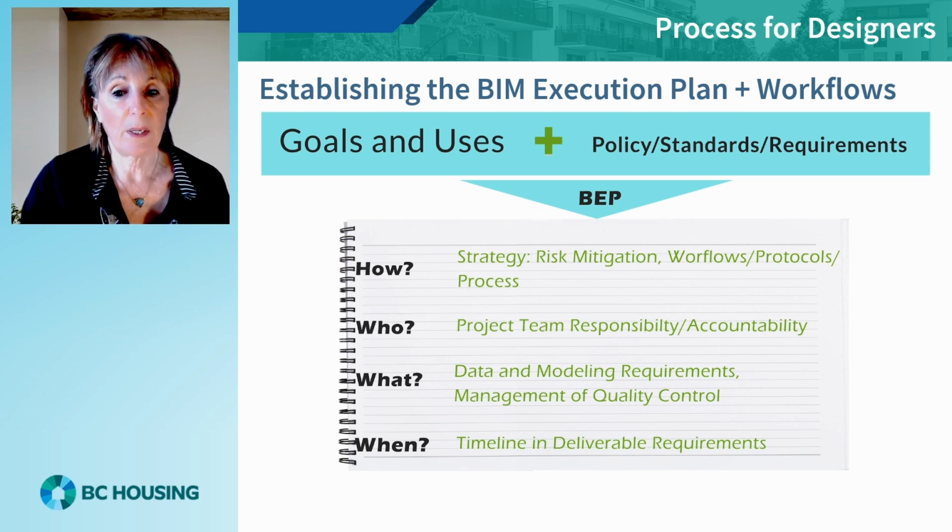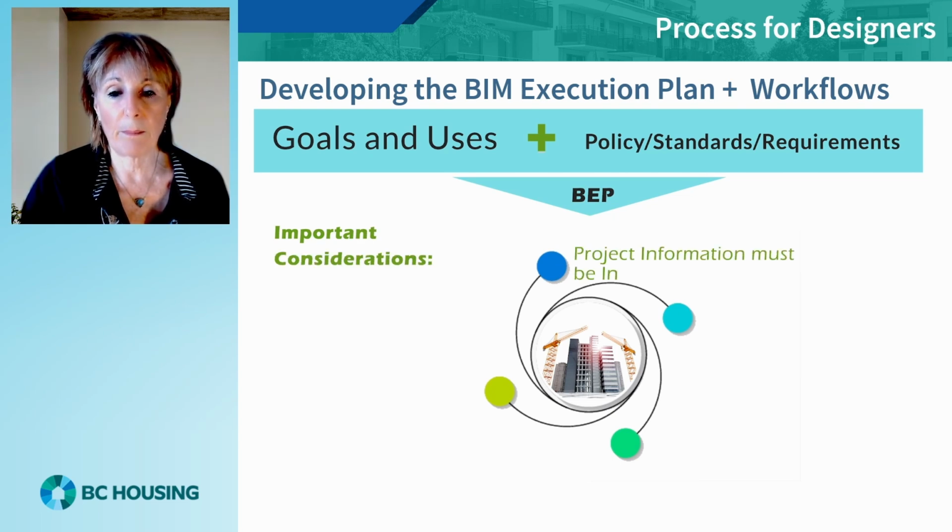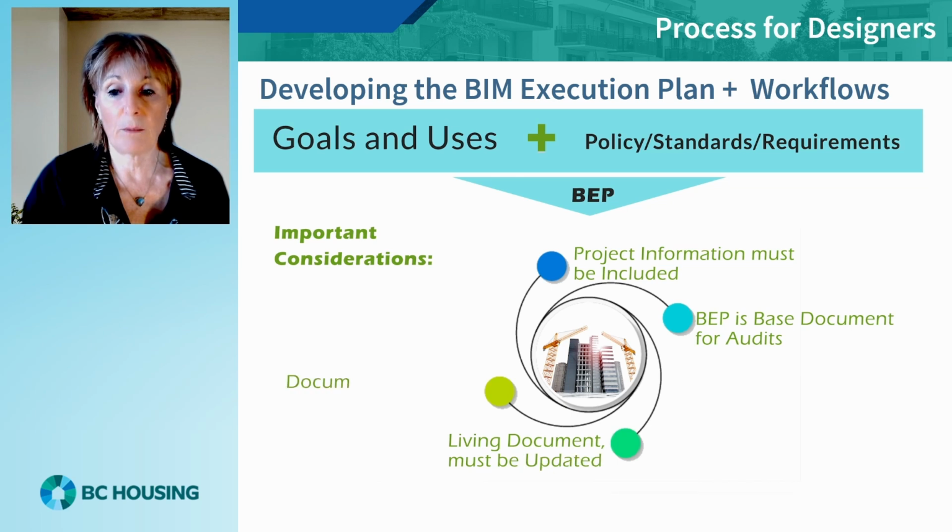Things to keep in mind when generating a BIM execution plan include the fundamental project information. Remember, the BEP is going to be used as the basis for model and data audits. It is a living document that will need to be updated during the project, and the final BEP is a record document for the project.